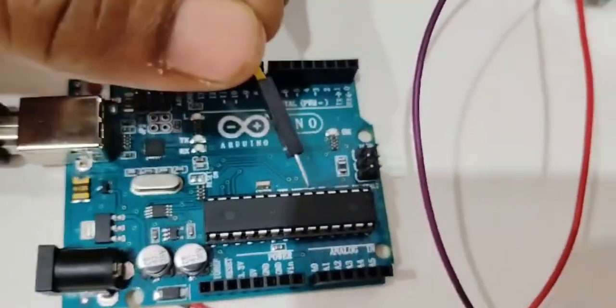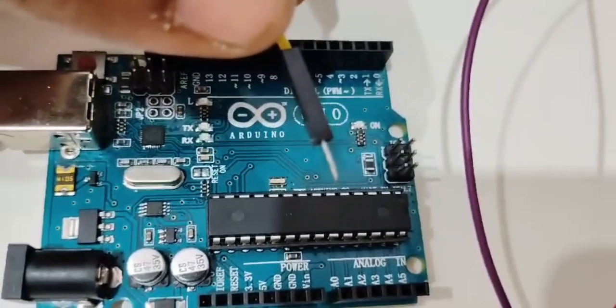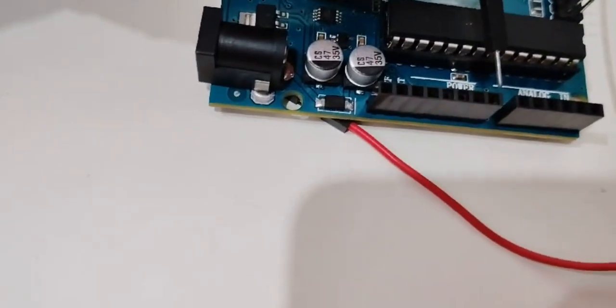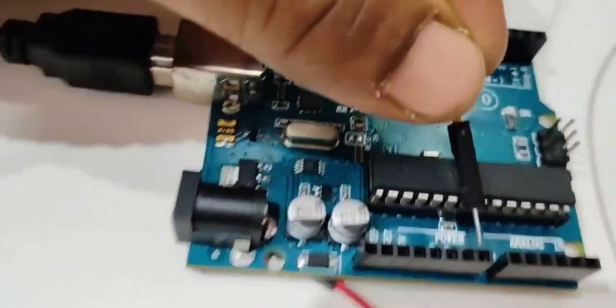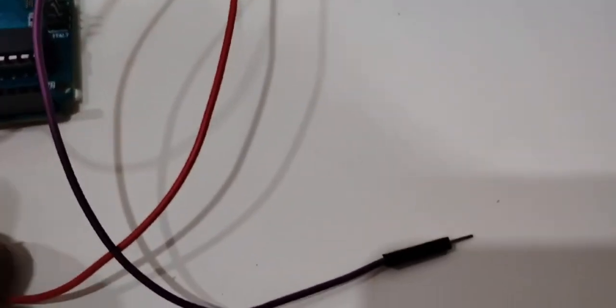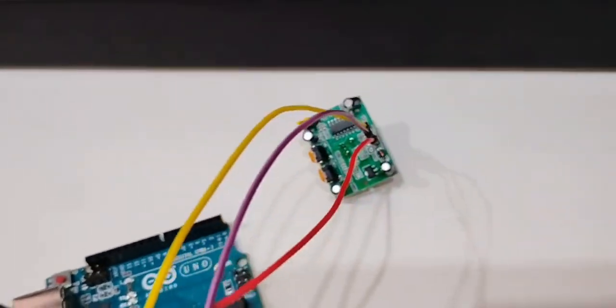I hope it is visible clearly. Yes, G and D you can see, and next to that you have the 5-volt supply. This is the Vin, ground. I'll connect to the ground. Then the red pin I will connect to the 5-volt supply, just next to that particular 5-volt pin. Okay, I have connected. And as per the code, we are going to connect the data pin of the PIR sensor